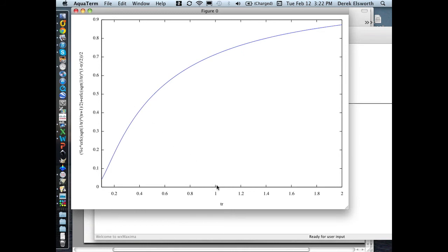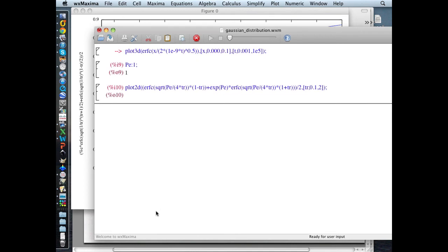Because now one pore volume has arrived, but now you have basically 70% of your concentration there. The 50% mark, the front that we were assuming before, has arrived after only half a pore volume has gone into the system. And so if you're looking at defining the behavior of arrivals, assuming that it's an advective system when it's a diffusive system, you'll be sadly surprised in an unconservative way, because things will arrive much earlier than you'd think.